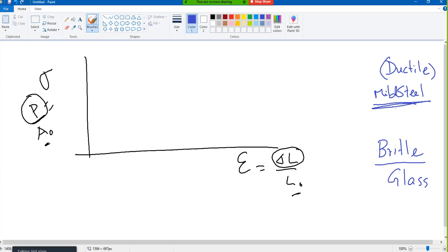But we like ductile material because it will show you that it is failing. It will give you some time, at least 1 month, 1 week. Even the mild steel we use in our reinforcement, if it fails, it will give you at least 2 years warning. Before that, it will elongate. There will be a lot of cracks, and by this time, you can easily vacate it.